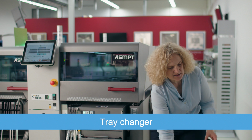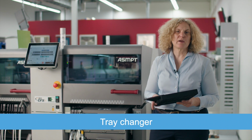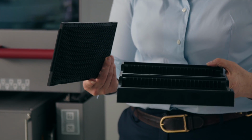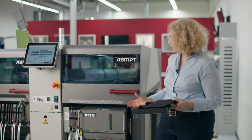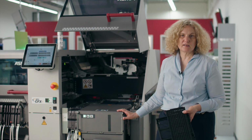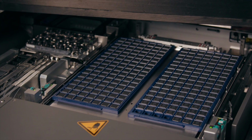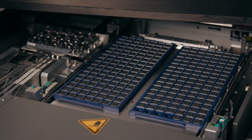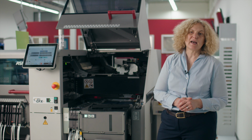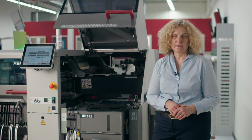In most cases, the last machine of the line needs to handle bulky trays of all kinds and heights. With the new tray unit for SIPLACE TX, this is an easy task. The tray unit can handle 2 JEDEC trays on a tray carrier or a large tray with a size of 355 by 275 millimeter.